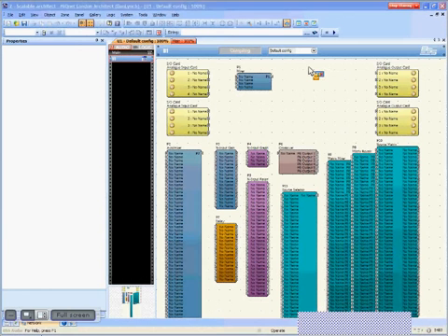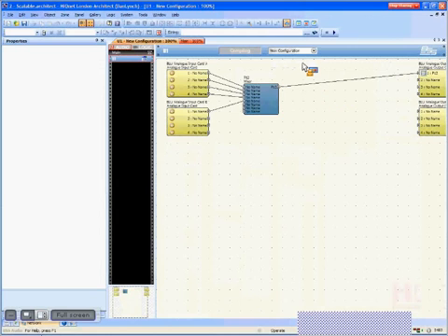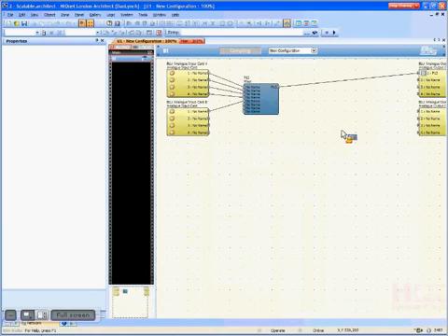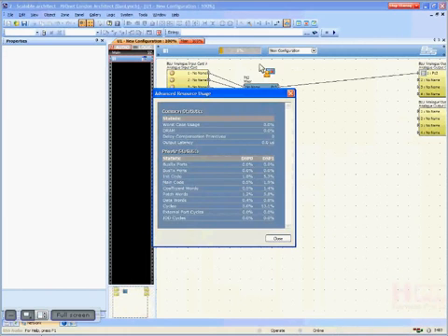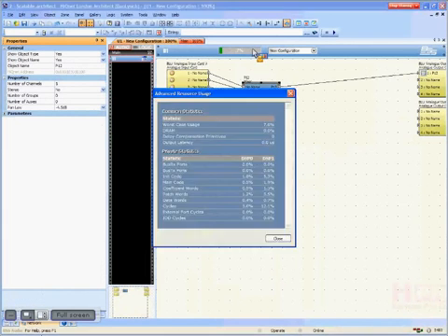You've all seen the scalable processing objects, but I just want to show you real quick why they're so important. If we have 5 mic signals being mixed down to 1 output, in the bad old days, we would put them in an 8-channel mixer. That would take roughly 8% of our total DSP power. With scalable processing objects, I can change that to a 5-channel mixer. And instead of taking 8%, it only takes 7.6%.